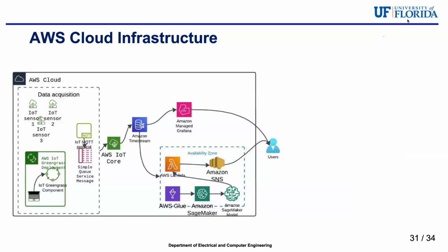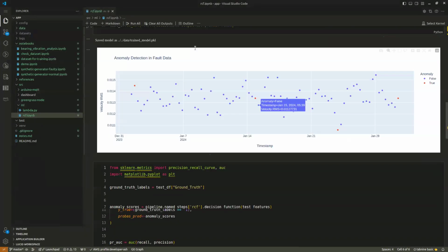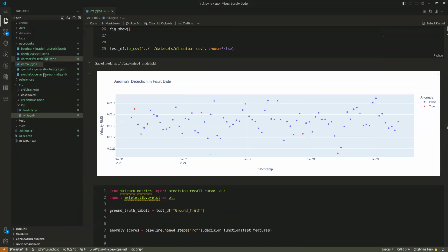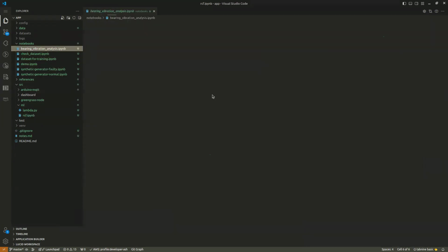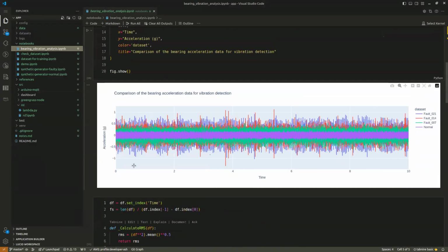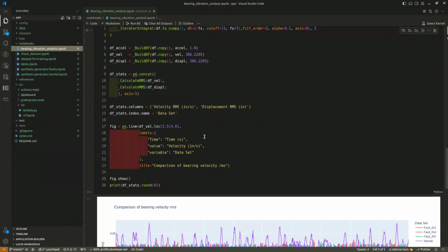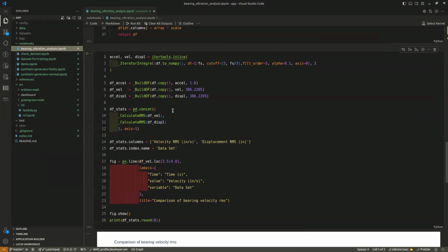Before going on with the demo, I want to explain the signal processing involved for the machine learning. As I said, this is the time series information that I got for 10 seconds, the actual ground truth information for vibration with fault and without fault, in normal working conditions. I'm using this information for training, inputting it to my program for finding velocity and displacement RMS.